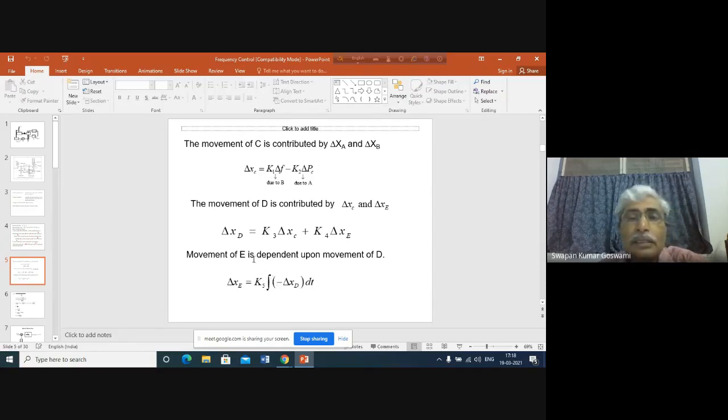Again, here is delta XC(s), put its value from this equation here, and then you can write an expression for delta XC(s) in terms of delta PC and delta F(s). Because delta PC is the power increase command, and delta F(s) is the change in frequency. We shall be interested to develop the expression in terms of delta F(s) and delta PC(s).